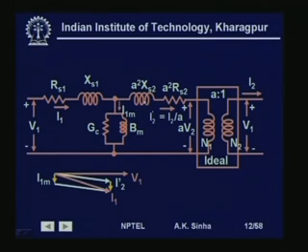Now, here again we can make an assumption that the current in this is basically reactive, in the sense that this is going to be almost 90 degrees with respect to the voltage, because this is much smaller and this is much larger. So, this is going to be like this, and if we have loaded this transformer, the power factor of the load will be around 0.8, 0.9. So, the current here is going to be almost in phase with the voltage, with a small angle here.